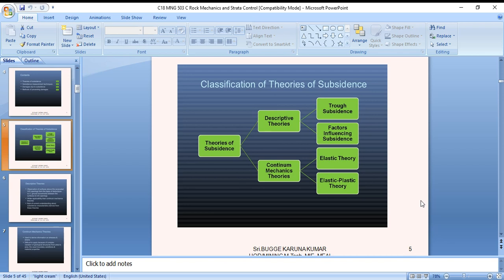Subsidence and caving are generally associated with incompetent rock, and many mining operations in which these processes occur are in rock that would be classified as such. However, there are exceptions. Some evaporite minerals in room and pillar mining, which are normally classified as competent rock, will deform without fracturing to the degree that an opening will be closed. The roof span is increased efficiently. Moreover, the expression of these subsurface subsidences may be evident on the surface, even though 1,000 feet or more are covered.